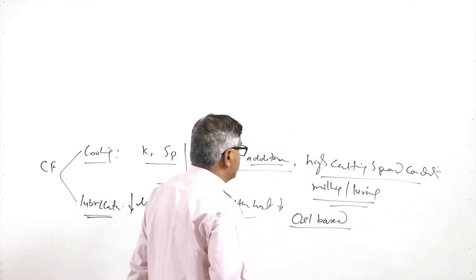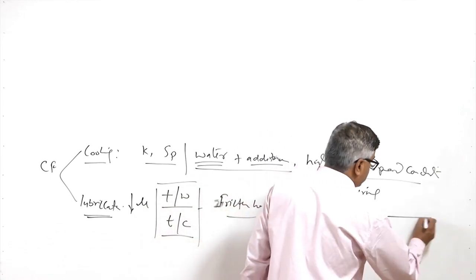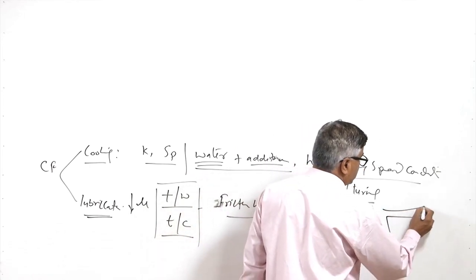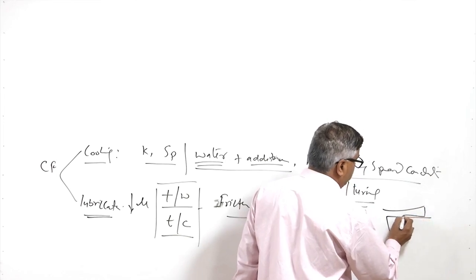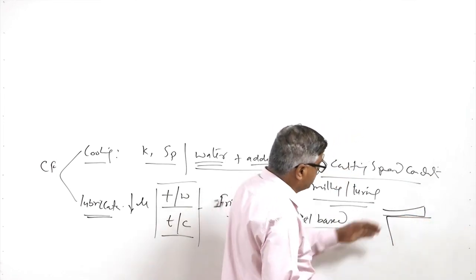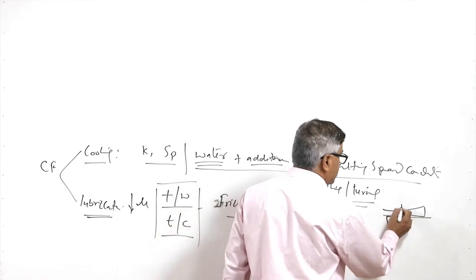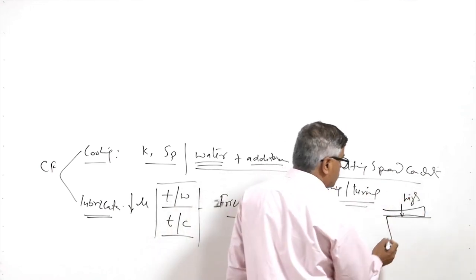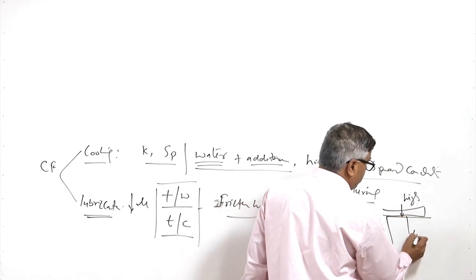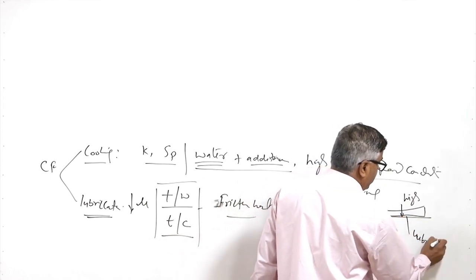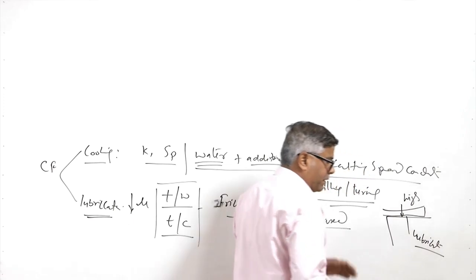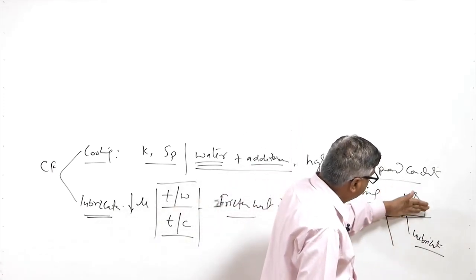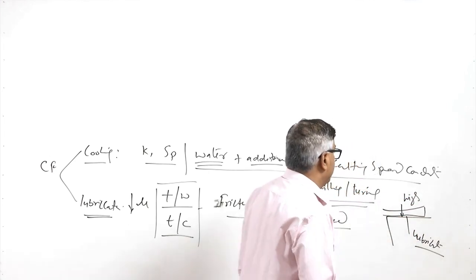But the stresses, or the pressure, which will be present during the flow of the chips over the face of the tool are high enough that any lubricant, if applied, will be made unstable, so that direct metal to metal contact between the chip and the tool is present.